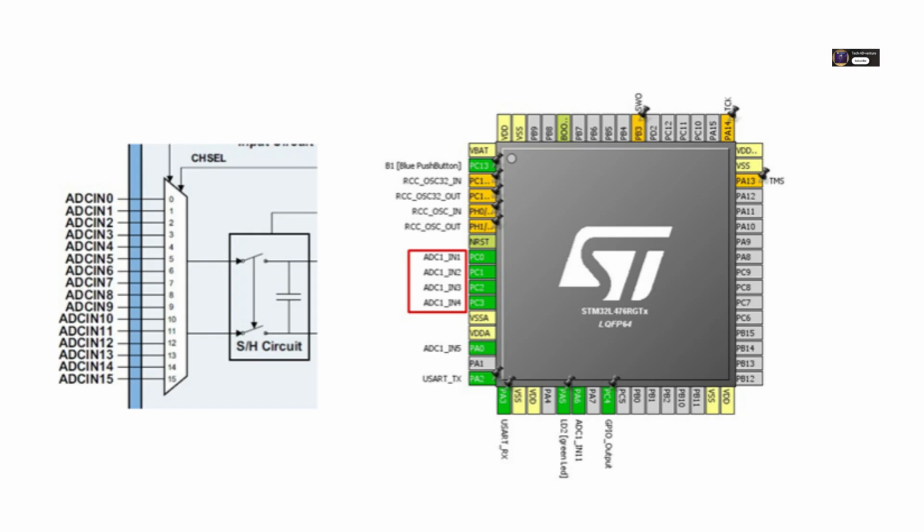You'll find these listed in the microcontroller's datasheet, like PA0 might be ADC1_IN0. Got it. Check the datasheet. Absolutely. Then, crucially, that pin must be configured in its analog input mode. This disconnects the digital input-output buffers from that pin, preventing them from interfering with the sensitive analog signal. No digital stuff messing with the analog signal.